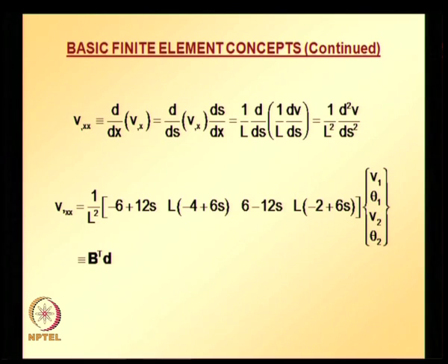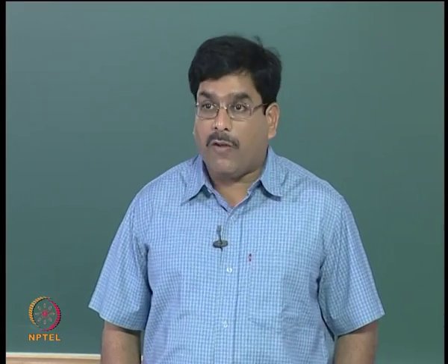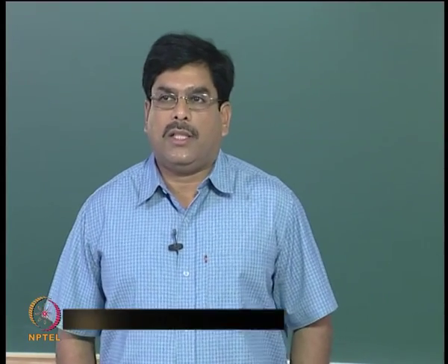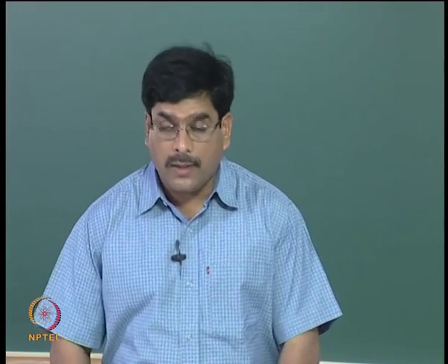If you observe this equation, it turns out that this equation is linear. So the two node beam element that we just developed captures bending moment accurately if the variation of bending moment is linear along the element length, because S is going from 0 to 1,